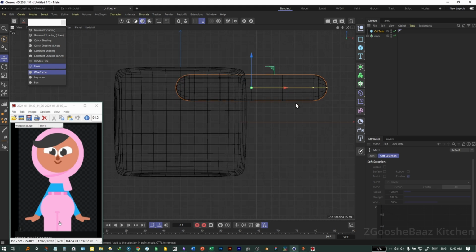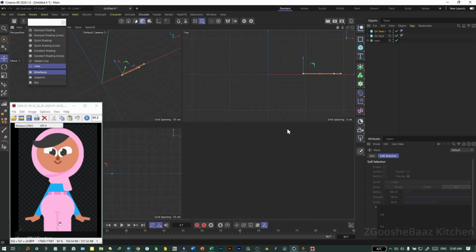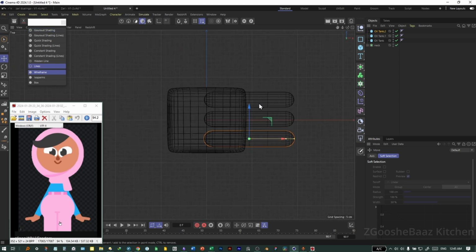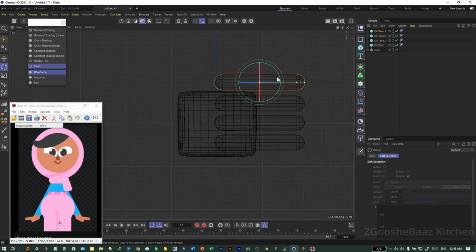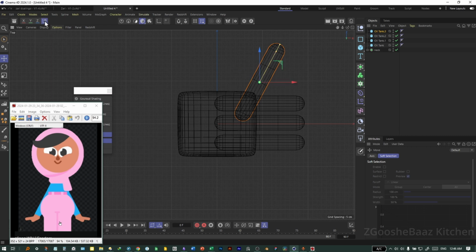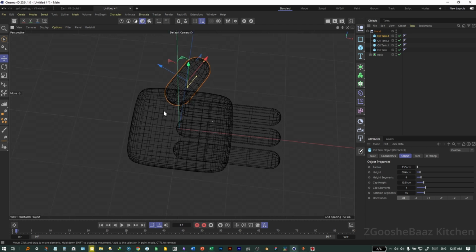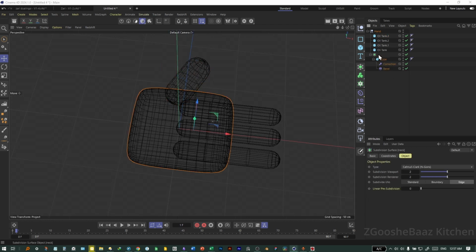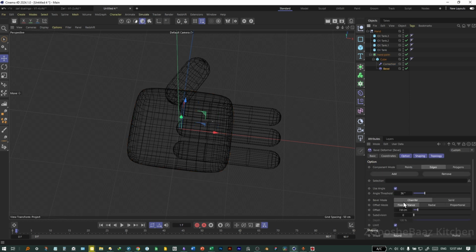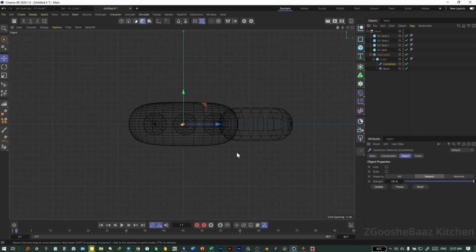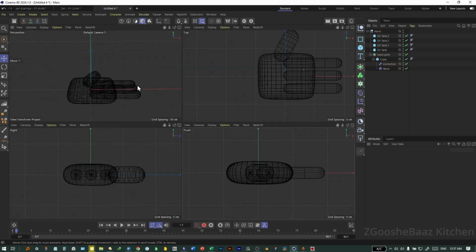Duplicate and offset each finger by holding Control, duplicating it. Okay, now we have 3 sausages. Duplicate it for the thumb, rotate it. I'm using W to change the transformation axis from local to global. Make this one shorter and bigger. Also change the height cap for it. Okay, these are my final values for the hand. For the bevel, I use 36 and 7/8 on offset. And you can see the width and height of the palm and fingers from the side.